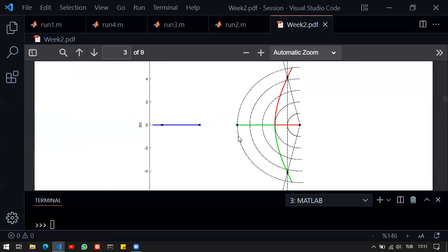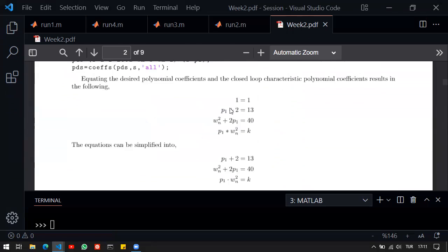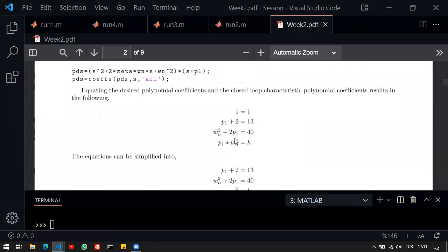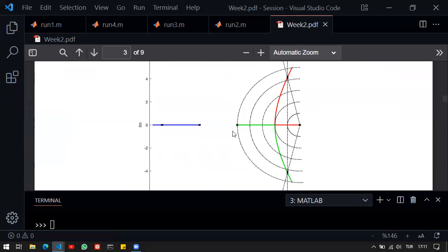Now, to remind you of the fact that I've used the algebraic method, where we use the polynomial coefficients to determine the exact values, to attack the problem from one side. And I've also used the root locus method to analyze my solutions and attack the problem from a different perspective. Therefore, you have to know that you need to use both methods simultaneously, because one of them is showing some perspective and the other one is completing the picture.